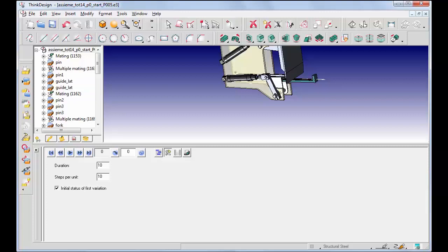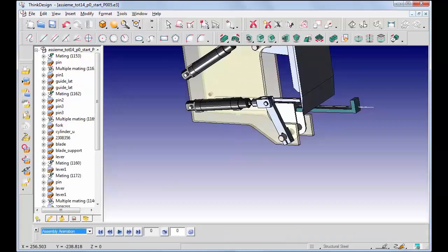The flag initial status of variation enables us to impose that the initial status of the first variation be reset any time you use the left button on top, the one moving the animation back to the initial position. At such an extent, we can try to launch our animation using the play button after iconizing the window and unhiding layers 10, 21, and 22. As we are doing, and you can easily see in our movie.